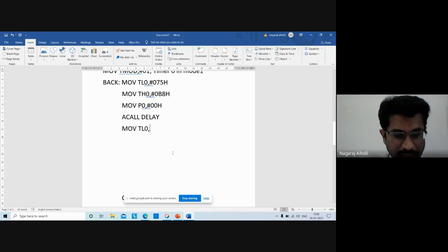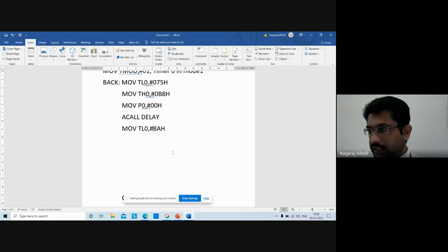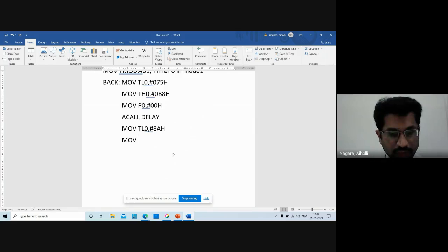So that is 8AH, okay, #8AH. Then MOV TH0, #, how much is it? 0EAH, or EA. So #0EAH.